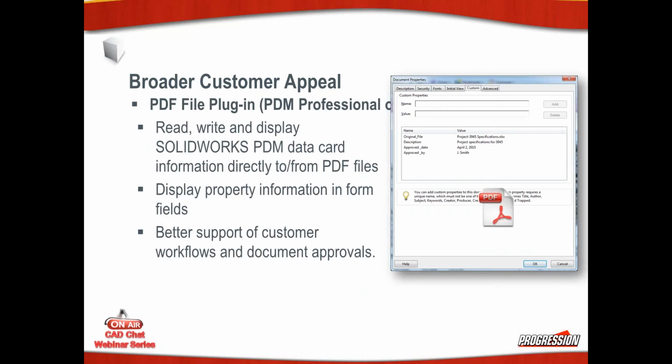Okay. So first of all, the PDF file plugin, as I said before, is going to allow us to read, write, and display SOLIDWORKS PDM data card information directly to the PDF file itself. This, as I said before, is very important to understand. So if we have the description, the approved by and approved dates, if there are fields in the PDF, they can be updated by writing this information to the custom property of that PDF, and that field then be linked to that variable, if you will, that custom property.